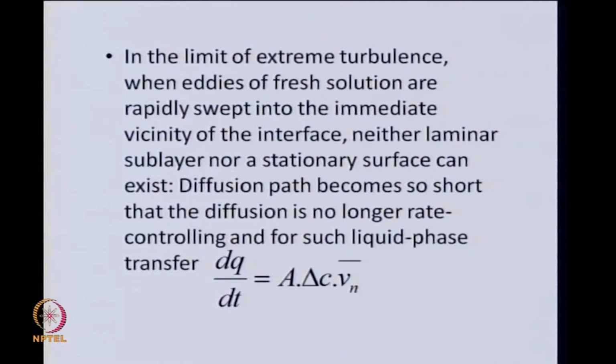It is not steady state, it is this momentary transport of the solute from bulk of liquid to the interface, and if that goes in the same proportion to the gas phase, at that point you may say there is a balance of the two, but steady state should not be brought in because this will not be a steady state picture. At another moment the Vn bar may differ. So, we only require that whatever is transported from bulk of liquid to the interface will be what will be going into the gas phase, and this Vn bar is the average.